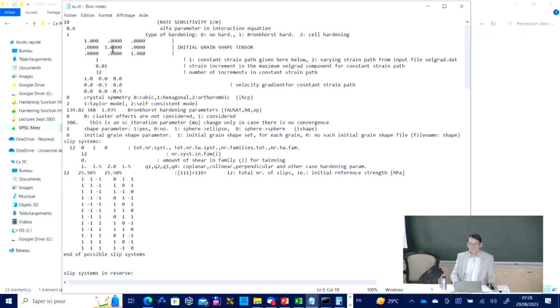This shape tensor is changing automatically as you deform the material. So here in tension, it will be elongating in the direction of tension. We will elongate the sample in direction 1. And then this value will be like 2 here, and these other values will be smaller than 1. This ellipse. There will be no shear in this testing, so the other elements here will remain 0. They correspond to shape change when there is a shear deformation.